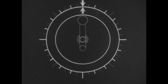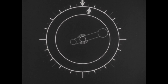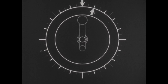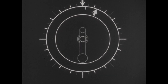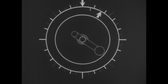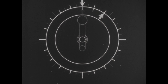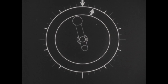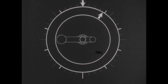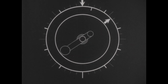If 20 cuts were wanted, 2 full turns of the crank would move the work 2/40ths or 1/20th of a complete revolution, locating each of the 20 cuts. If 10 cuts were wanted, 4 full turns of the crank would move the work 4/40ths or 1/10th of a complete revolution, locating each of the 10 cuts.